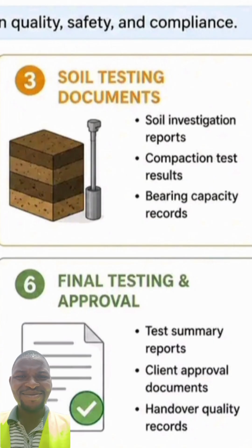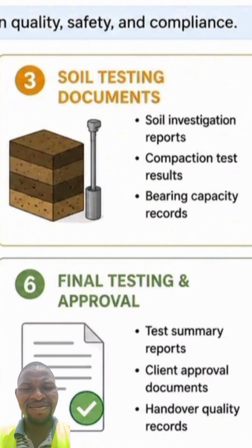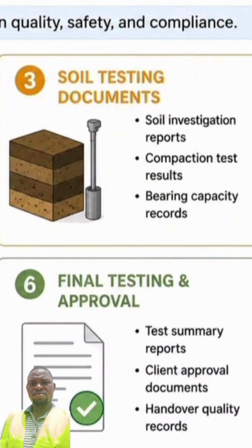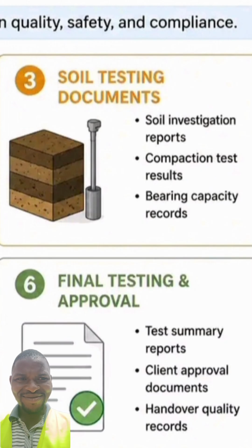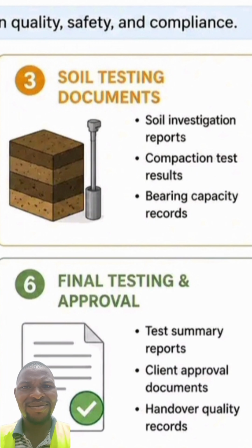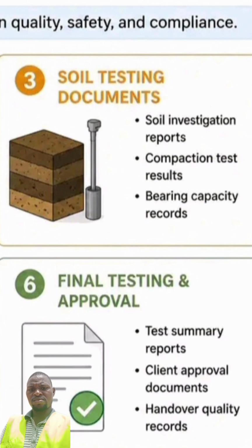Then we have the compaction test result. The compaction test result is also an important test you tend to carry out, because once you've done your refill and you compacted in layers, you do your compaction test. So the result of that compaction test is what we are referring to here. It is very, very important you know if the compaction you've done will be able to carry the weight coming on it. That is the foundation weight.